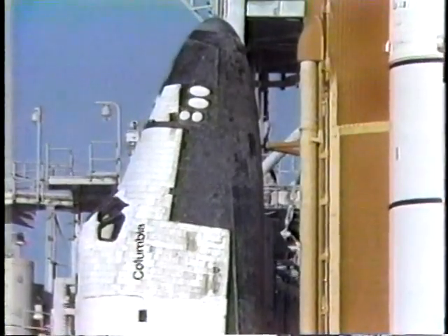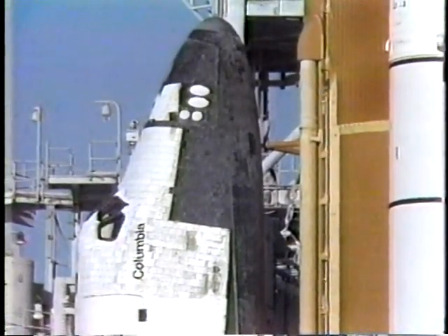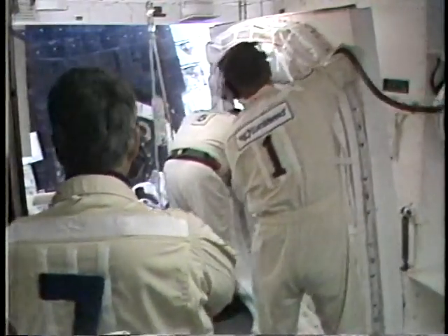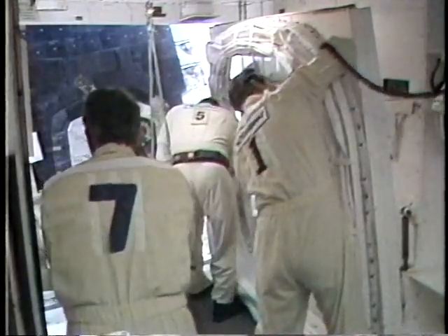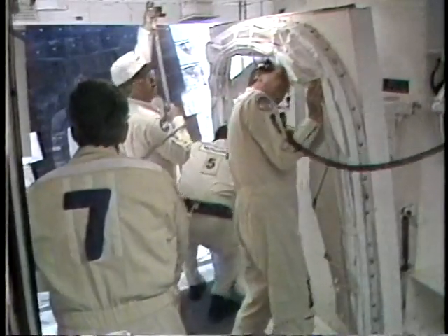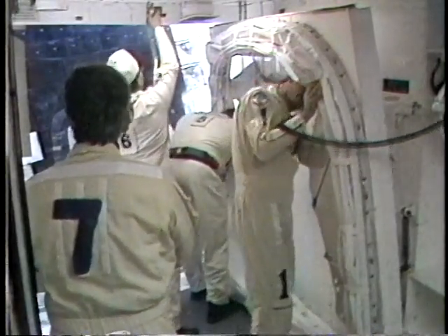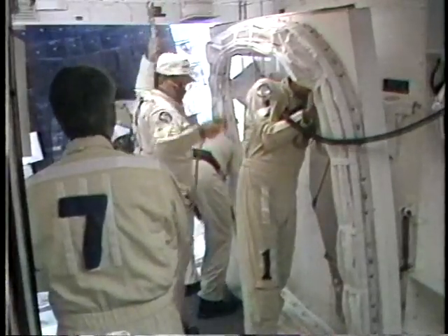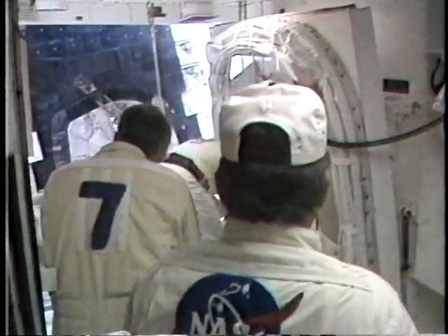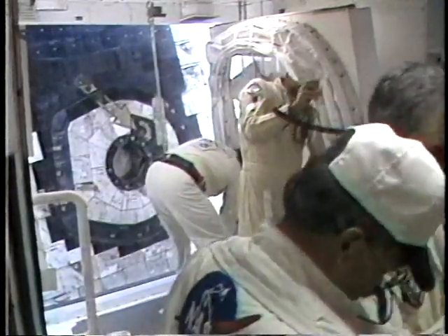Everything continues to go well, and once the White Room closeout crew is down off the pad, which should be in the next few minutes, then the fixed service structure elevator will be locked into place on the ground. Also at this point in the count, the orbital maneuvering system gaseous nitrogen tanks have been pressurized. The pre-flight checks of the orbiter's master events controller is also being completed. This is the software package that relays commands from the orbiter's computers to fire explosive charges that are connected to the solid rocket booster hold-down bolts at the launch pad, and this occurs at launch time T0.